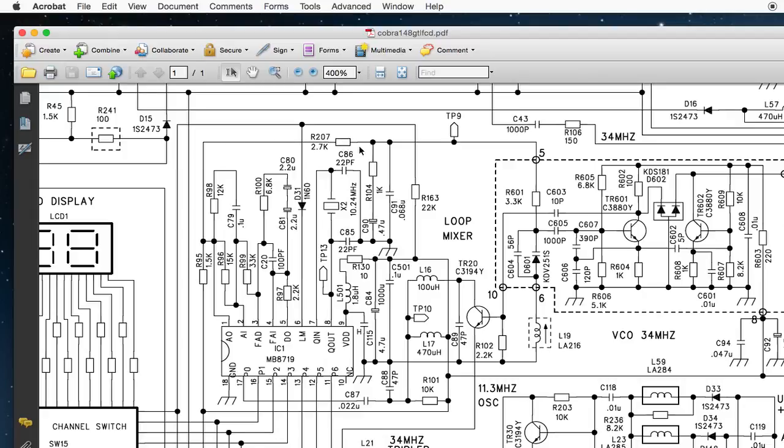So that's feeding through that resistor. Here is the capacitor network. As the second example, effectively there's a resistor and capacitor in series, and there's another capacitor next to that in parallel. That takes out the higher frequency, and this takes out the lower frequency stuff, smooths that out. This resistor value can be adjusted to affect the responsiveness of the phase detector signal, so how much of the pulse it smooths out.